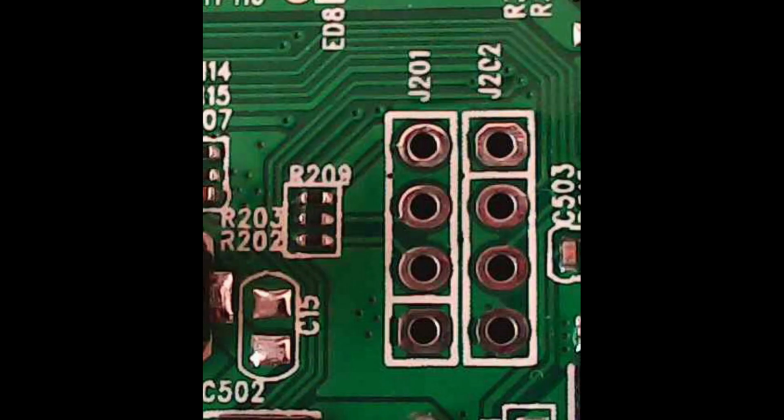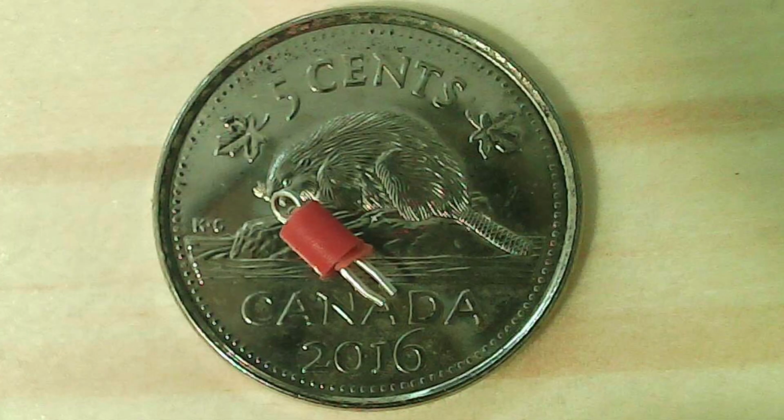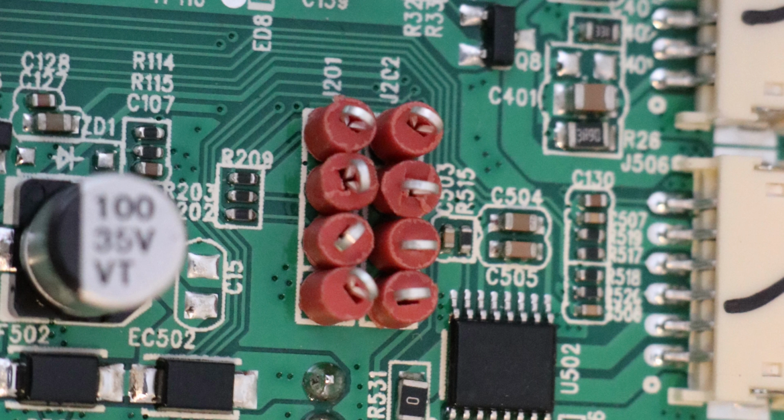One very interesting feature on the circuit board is the set of through holes. These look like they're for a couple of jumpers, and I bet one of them is for a UART to communicate with the CPU directly. Now, they're not populated, so they're awkward to connect to, but we can just populate them with some of these tiny little PCB test points, which are very cheap, a couple of bucks for 100, and we'll be good to go. Here we see the 2 sets of jumper through holes with the PCB test pins inserted.